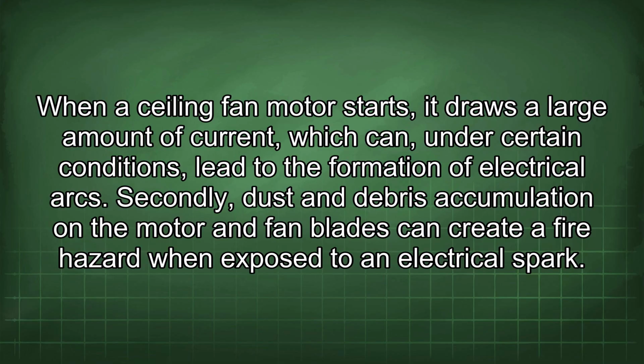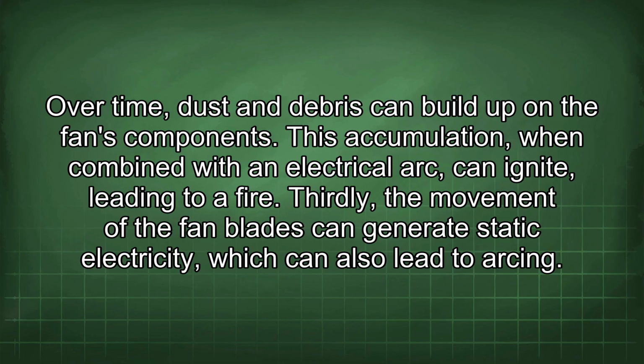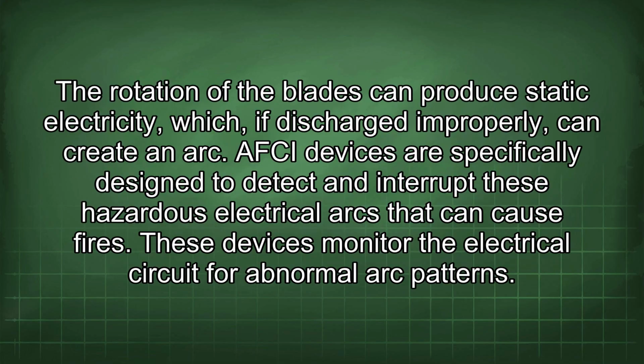Secondly, dust and debris accumulation on the motor and fan blades can create a fire hazard when exposed to an electrical spark. Over time, dust and debris can build up on the fan's components. This accumulation, when combined with an electrical arc, can ignite, leading to a fire. Thirdly, the movement of the fan blades can generate static electricity, which can also lead to arcing. The rotation of the blades can produce static electricity, which, if discharged improperly, can create an arc.